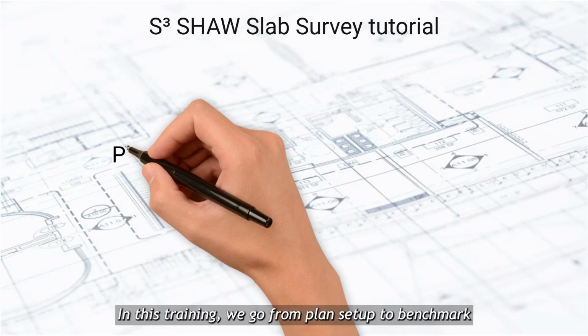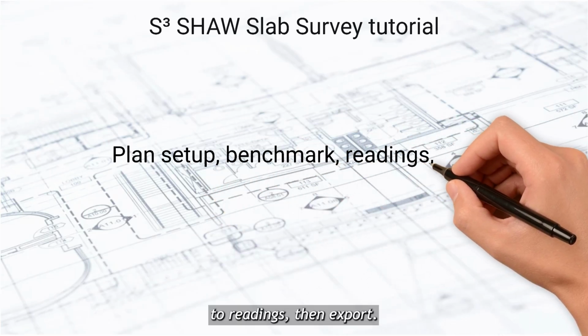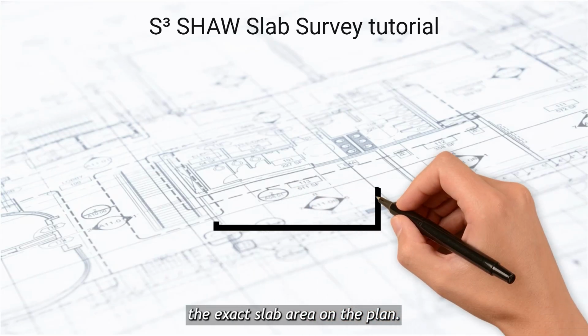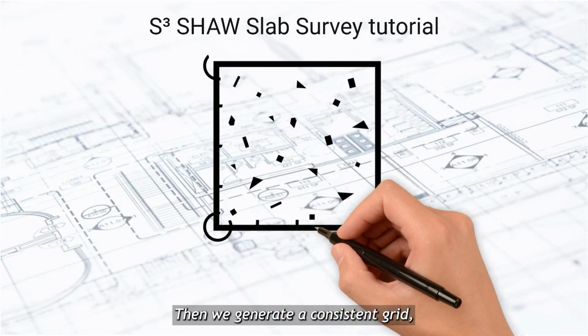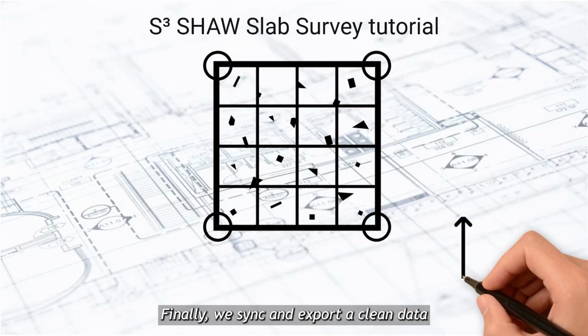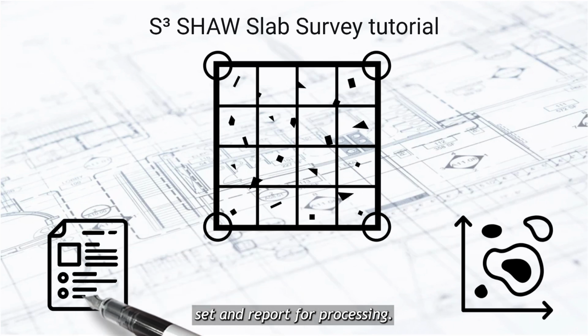In this training, we go from plan setup to benchmark to readings, then export. We start by defining the exact slab area on the plan. Then we generate a consistent grid so readings follow a repeatable pattern. Finally, we sync and export a clean dataset and report for processing.